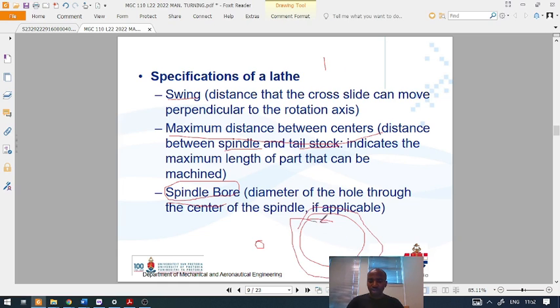The longer they are, the diameter is going to increase, because you don't want a long component that wobbles and dances around when you rotate it. Don't want that. So even with this method, we still have to balance them out if they are very long. If you have a spindle on this side and a tailstock this far, at 2 meters, maybe at 1 meter you want to put another supporting component. This will be a support with rollers to allow this thing to rotate. This will be your tailstock.